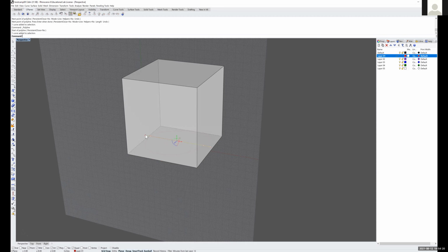How did you get the CPlane again? The C-plane's really, really important. I think I chose front. When we start, the default is the XY plane, and by changing it to front, back, left or right, it'll flip it up.